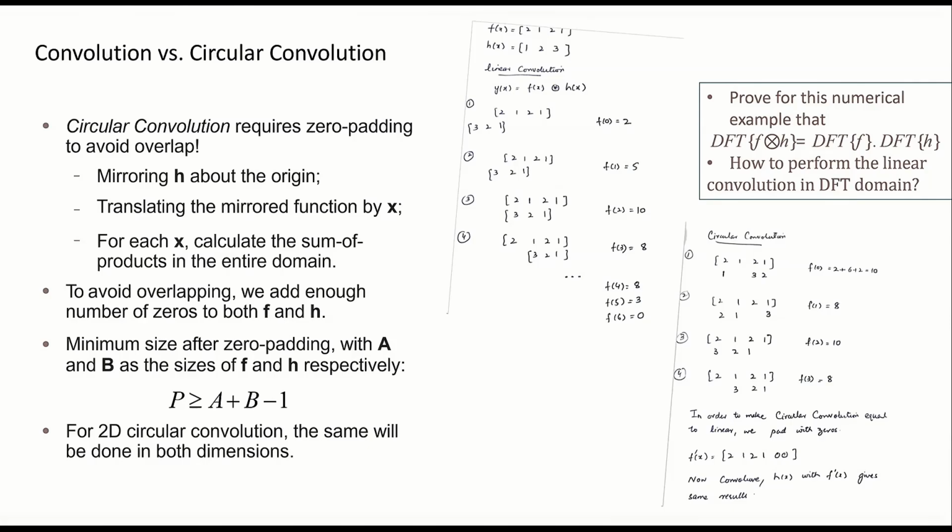Origin and starts. You mean this one? Yeah. Now see, there are two things. When I'm talking about the simple convolution, this is general convolution, so I'm not talking about where 0 is. We have to multiply and do it. The one you are talking about is the one where we are doing filtering, in which we assume the 0 is in the middle. So that is a special case of the convolution. Don't confuse yourself. Even if you take this as 0, no problem. You will get the same answer. So this is a linear convolution.